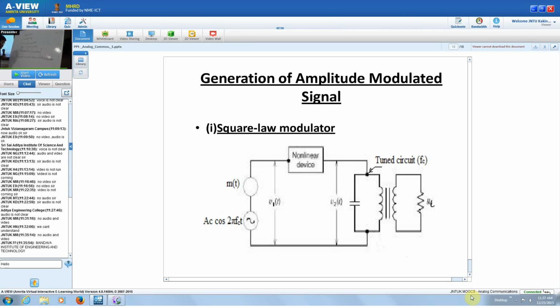Therefore, this is rewritten as a Ac times (1 plus 2b/a m(t)) cos omega_c t, because we have taken a Ac cos omega_c t out as a common factor, combining the first and last terms here. The remaining terms are a m(t) plus b m squared(t) plus b Ac squared cos squared omega_c t.